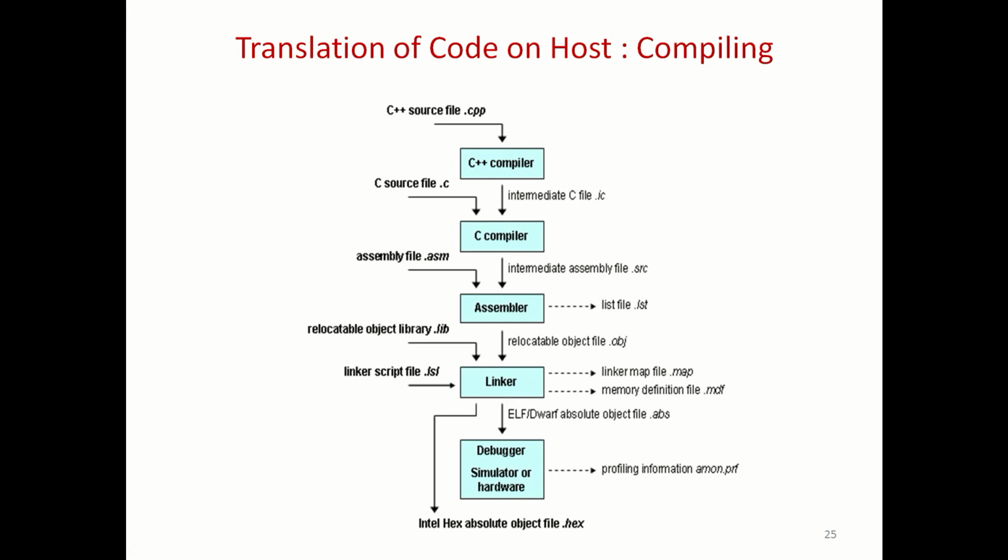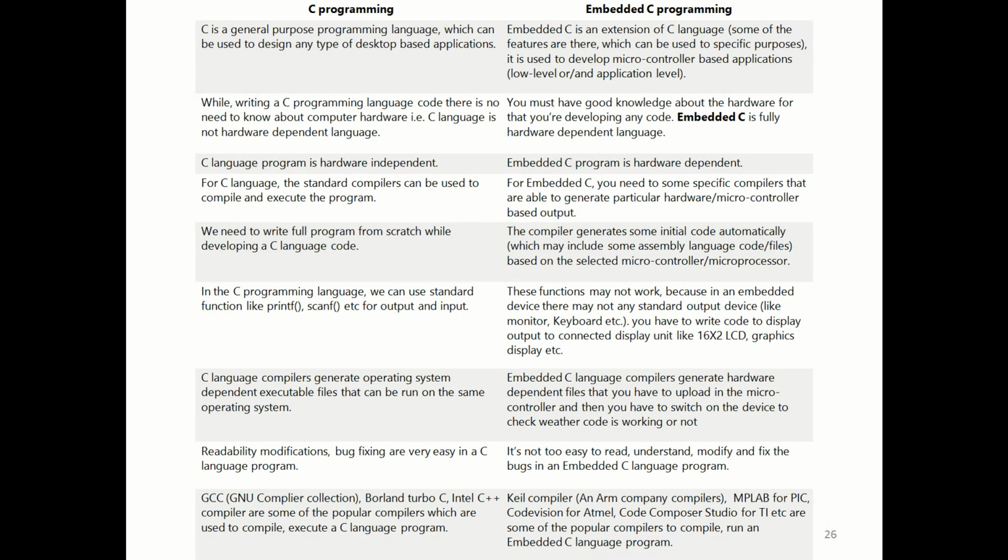That's why this is called a hex file, Intel hex file, which is absolute memory mapping, no relocatability. So our programming structure is more or less the same as a computer, but at the end there is a difference: absolute addressing, because we are not dynamically relocating from secondary memory to primary memory. Within the primary memory also, the address does not change based on the situation. That doesn't happen outside a computer because there is no Microsoft or Linux operating system here.